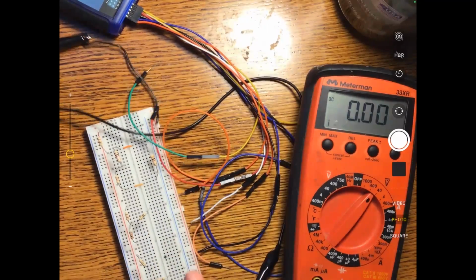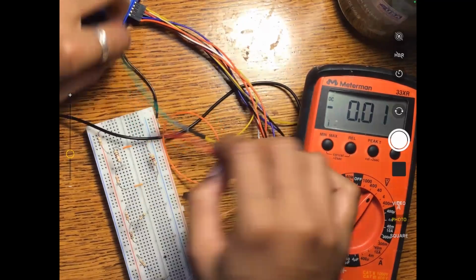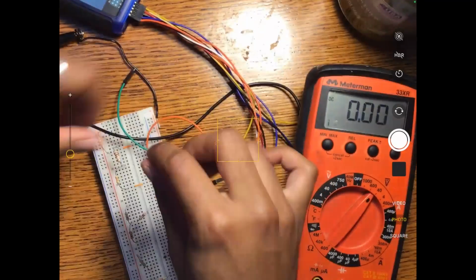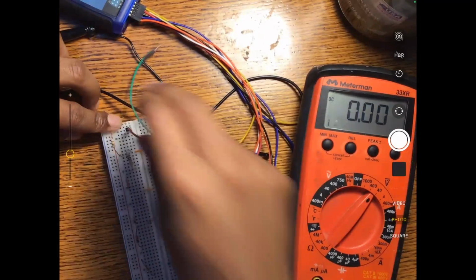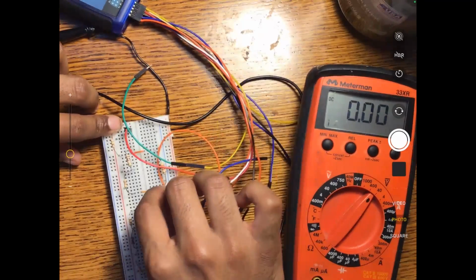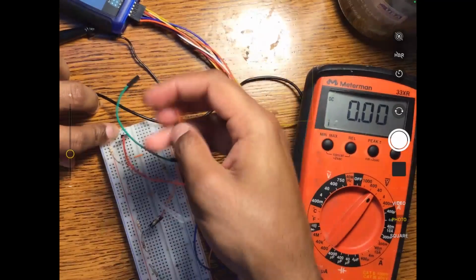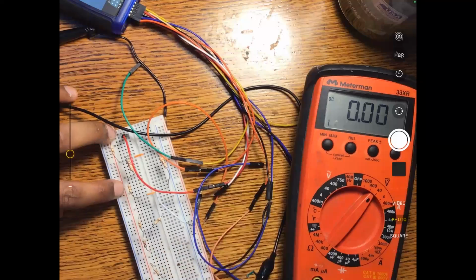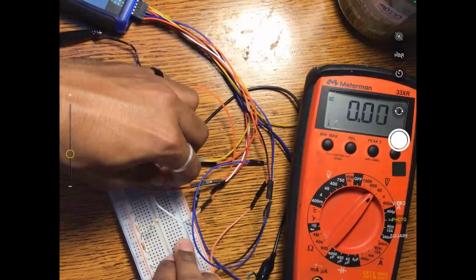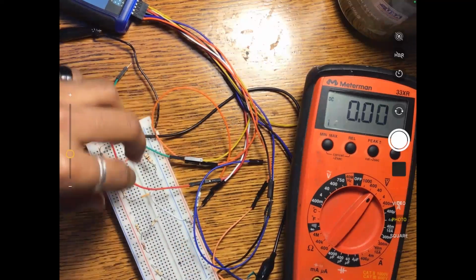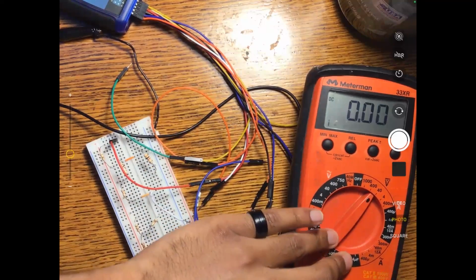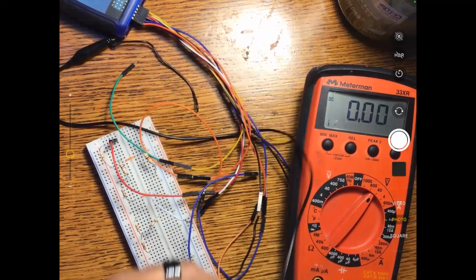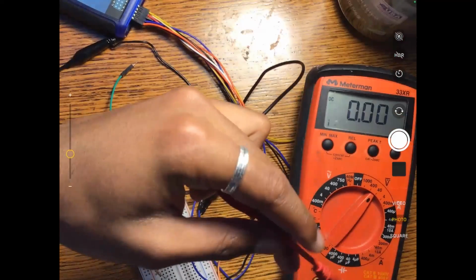So now I'm going to connect my voltage supply. So I need output 10 volts. So I'm going to connect the +5, the top, and then -5 at my ground. And then I want to measure the current flowing through R2. So if I want to do that, I have to actually remove this 3K and then push it up so that way I can place my multimeter in series with the circuit.